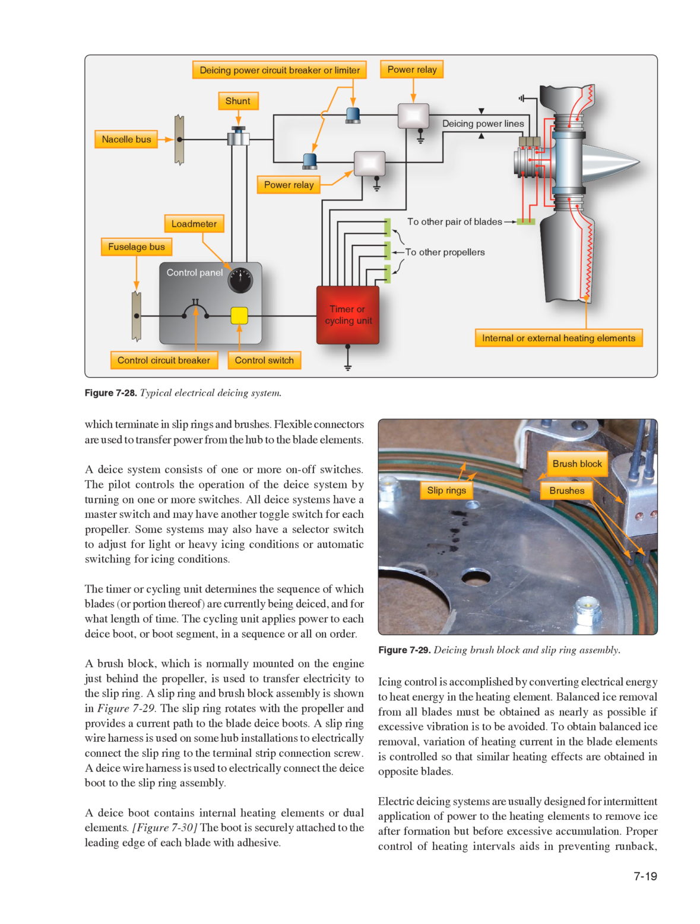The timer or cycling unit determines the sequence of which blades, or portion thereof, are currently being deiced, and for what length of time. The cycling unit applies power to each deice boot, or boot segment, in a sequence or all on order.